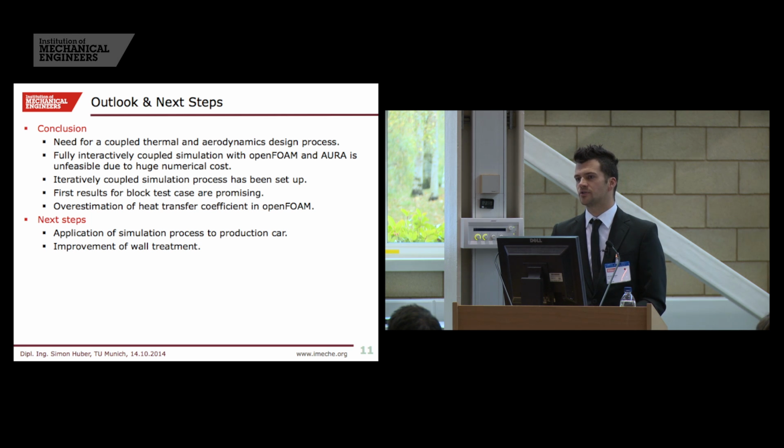And there's no advantage for the compressible solver. So the next task would be to apply this simulation process onto the productive car, and of course to improve the wall treatment and the result for the heat transfer coefficient out of the CFD simulation.